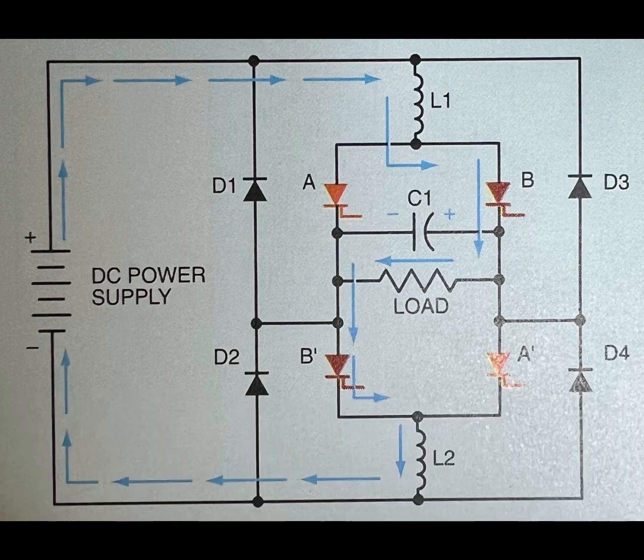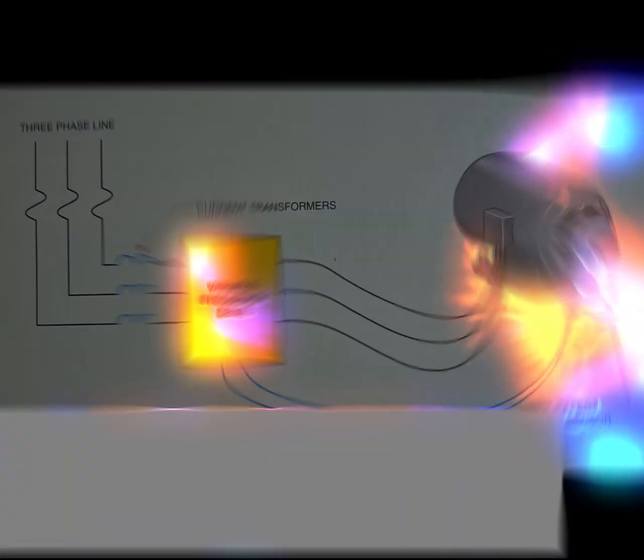Features of variable frequency controls. Although the primary purpose of a variable frequency drive is to provide speed control for an AC motor, most drives provide functions that other types of controls do not. Many variable frequency drives can provide the constant speed torque characteristics that are so desirable in DC motors. It is this feature that allows AC squirrel cage motors to replace DC motors for many applications.